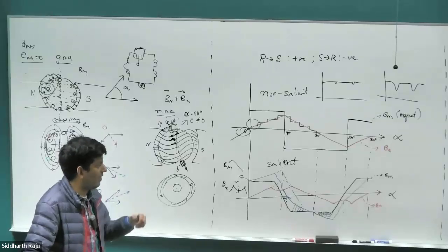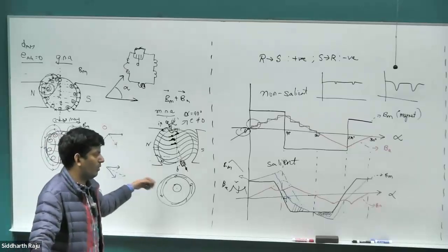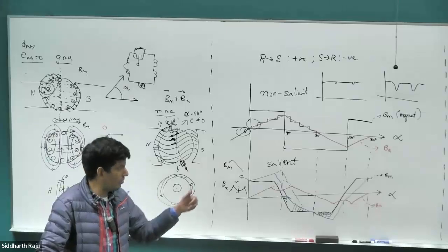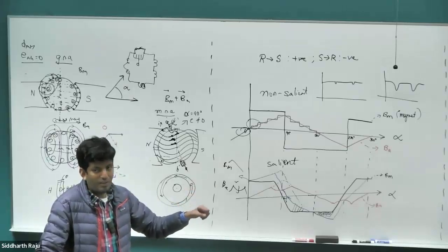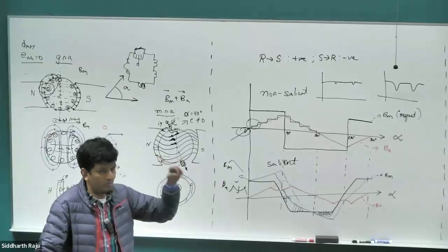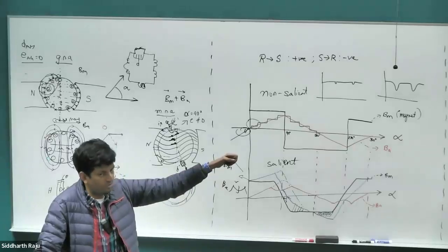It's not exactly at 90 degrees. There'll be a tiny offset. That's a very reasonable solution for low power motors because your core does not saturate for low power motors typically. But for high power motors, the core does typically saturate at rated current. And once it saturates, you end up with the problem where even a slightly higher amount of torque could completely stall the motor. And a stalled motor is a very big problem because if the EMF goes to zero,